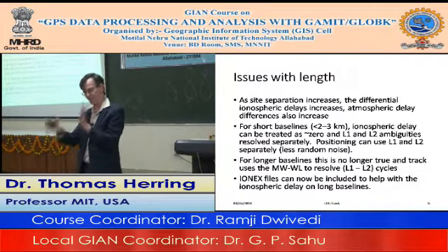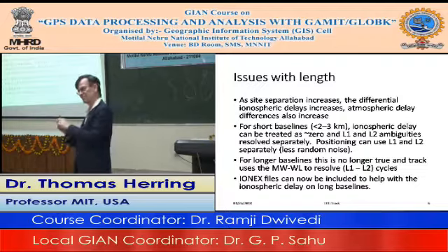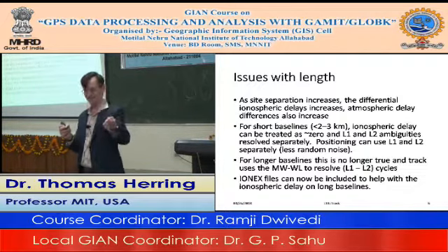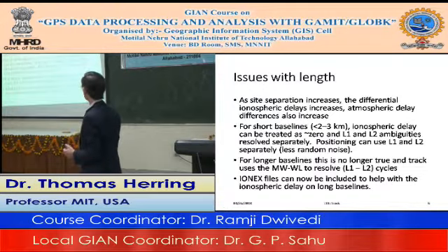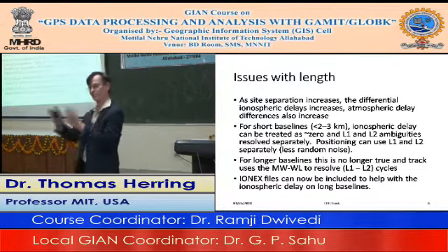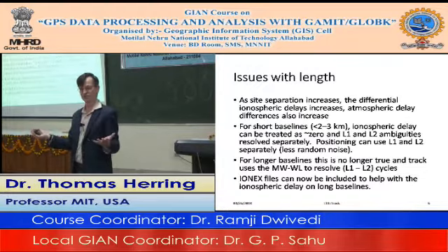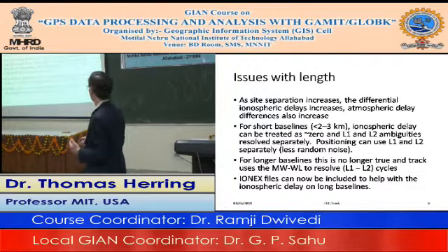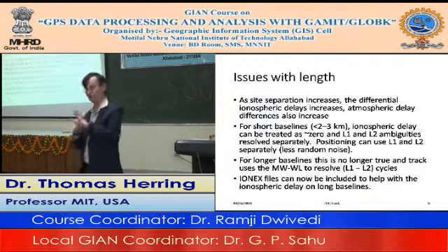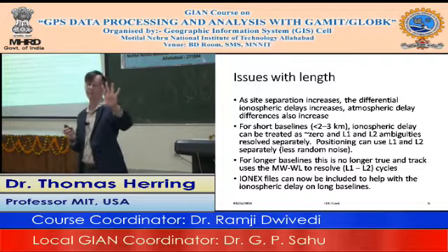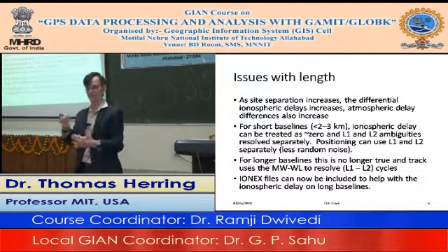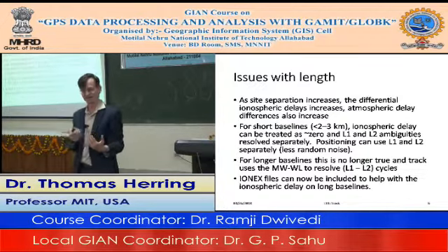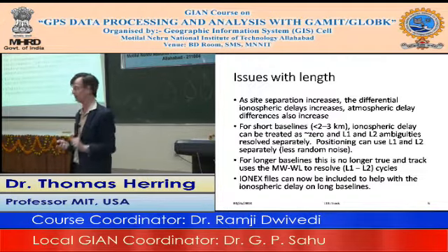So if you've got gaps in your data because your kinematic receiver's been going underneath trees and things like that, breaking up the sequence, it makes it more difficult. The atmospheric delay, in general, the further apart you get, the larger the difference in the atmospheric delay. And again, if you're doing a kinematic survey where there are massive thunderstorms off to one side of you, all the GPS signals coming through those thunderstorms are going to be incredibly delayed by the water vapor in those thunderstorms, and that will make your processing much, much more difficult.